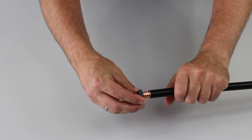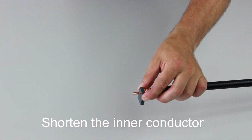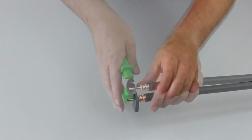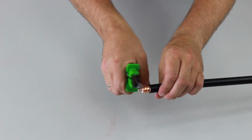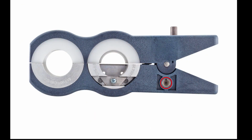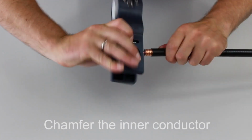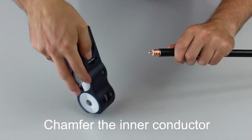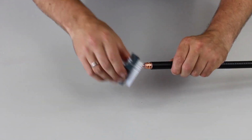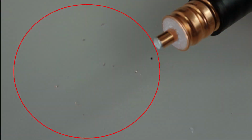In order to shorten the inner conductor to the correct length, use the gauge to then mark the length specified in the assembly instructions with a knife. Use the cable shears to obtain a clean round cut at the mark without deforming the inner conductor. Use the marked tool integrated into the Uniprep tool to chamfer the inner conductor. Work with side-to-side motions and turn the tool once, since it only has a cutting edge at 180 degrees. Remove the dirt on the inner conductor with the brush.